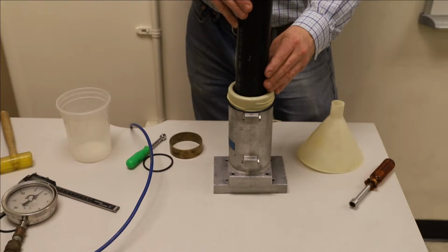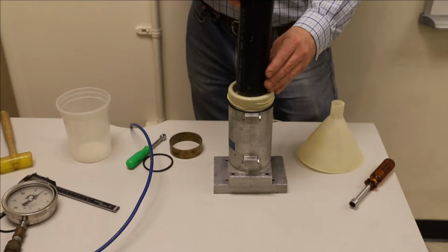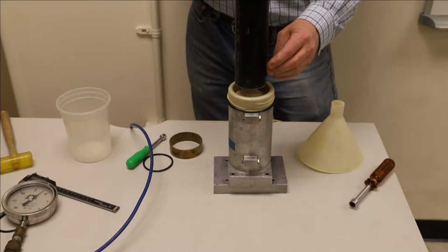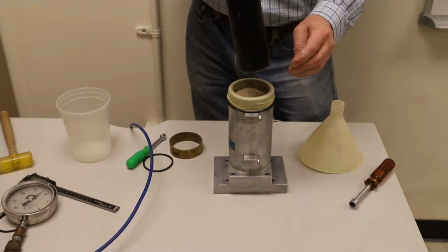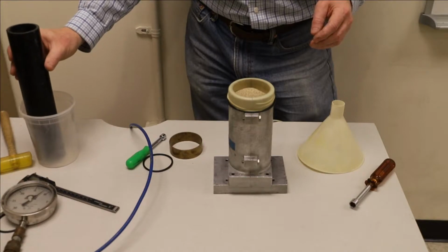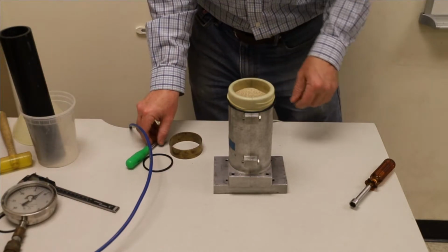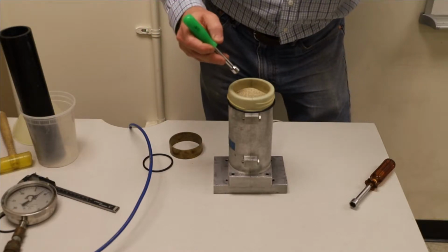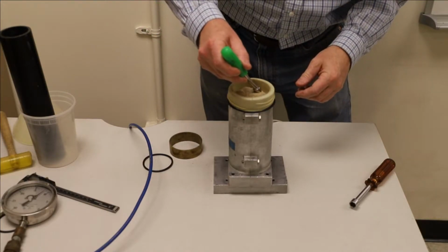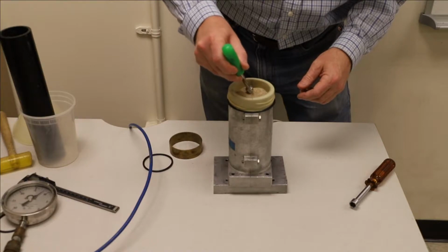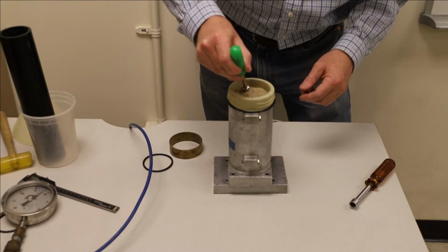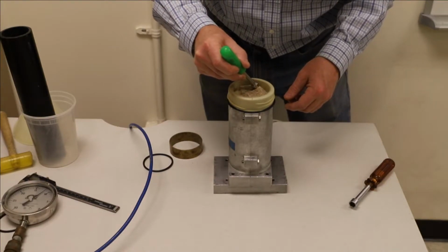We'll reuse exactly the same mass of sand, same grains in fact, to run the second specimen, the higher density specimen, when we build that in a little bit after we test this one. Alright, so there's our specimen, and we want to flatten out the surface a little bit so when we put the top cap on, it's nice and level.